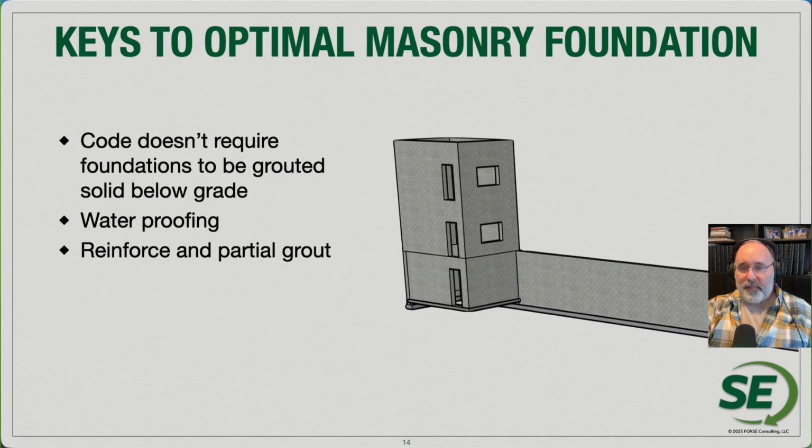But then going beyond some of those different guides, the code doesn't require foundations to be grouted solid. We know that there's important steps to make it successful. One of the things that does not make it successful is just simply grouting it solid. Getting the water away and the site sloping away from the wall, waterproofing, reinforcement, and dowels are all important. But solid grouting the wall doesn't provide any protection from the overall design. There's other steps that we pointed to are going to be really important.